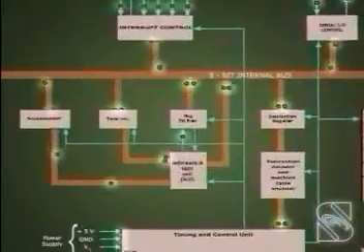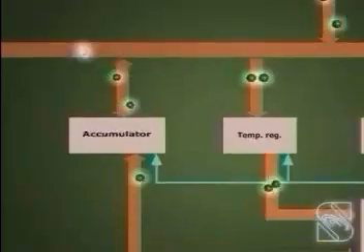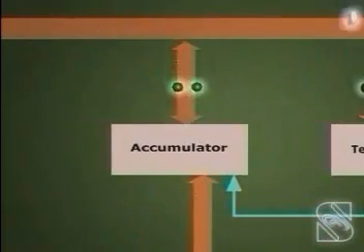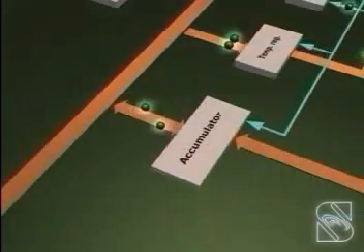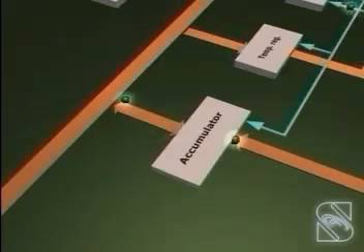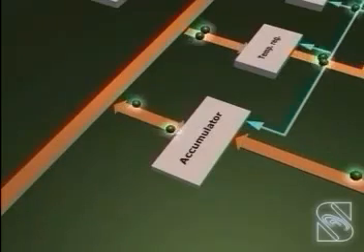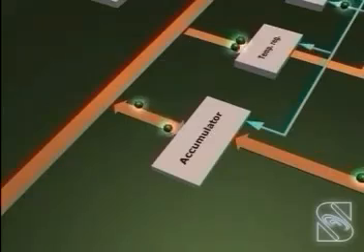Accumulator. Accumulator is an 8-bit register. It holds one of the data to be processed by Arithmetic Logic Unit or ALU. It also stores the result of the operation. The accumulator is also called the A register.